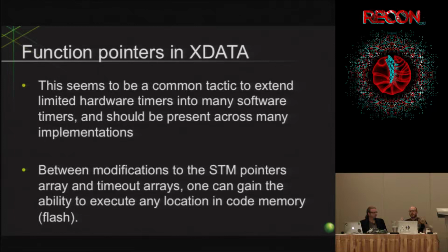So you reach in with the vulnerability one time, and you write the arguments that you want. You put those somewhere to start setting up your function call. You write these, you write these, you write these, and then you finally go in and overwrite the pointer that's actually going to give you execution. And by that time, RAM's already been modified, right? Worst case scenario is that maybe you're doing some sort of flash write operation, and the arguments being passed to flash write are now corrupted. So you think what that would do, right? Suddenly it's writing something unknown to some other unknown section of Flash, which is a really, really bad scenario for all exploitation scenarios.